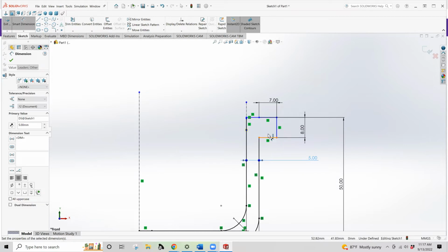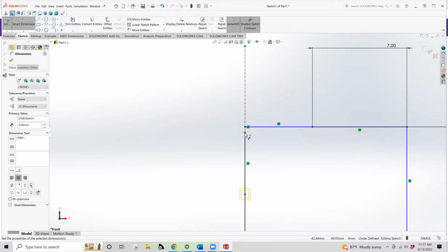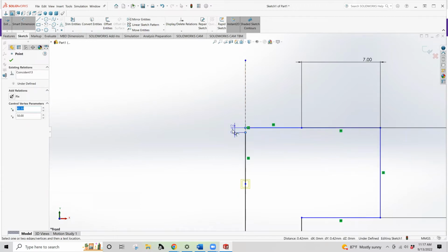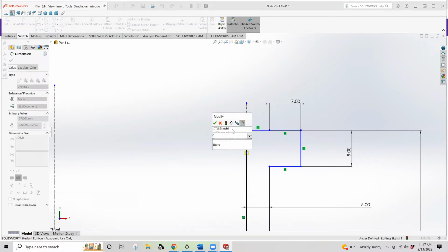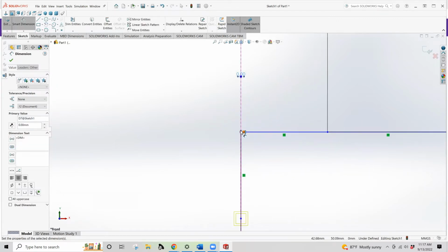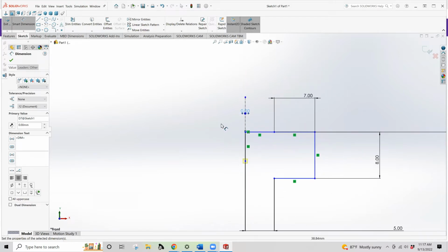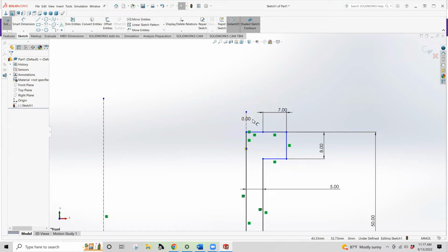I'm going to come in and make some changes there, but one of the things that we can check for is whether or not that is a watertight volume. So this, we actually can use the smart dimension to set to a thickness of 0 to make them coincident. So now we have coincident points, and that association will remain. So we hit escape. So if you guys leave a dimension of 0 on a finished part or something, then I'll know where that came from.